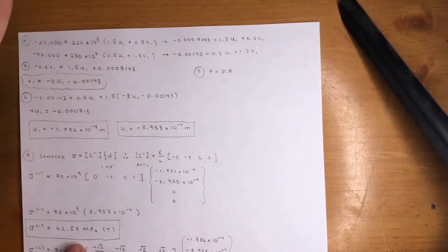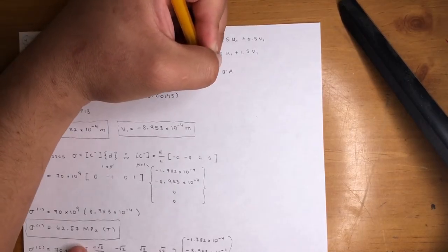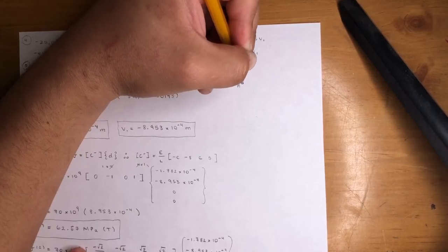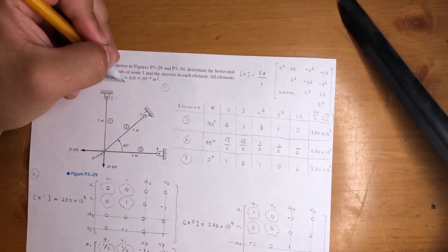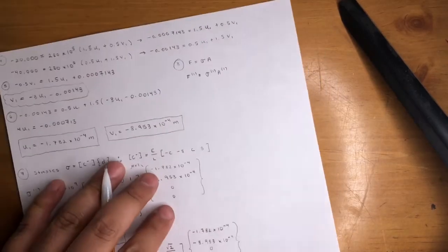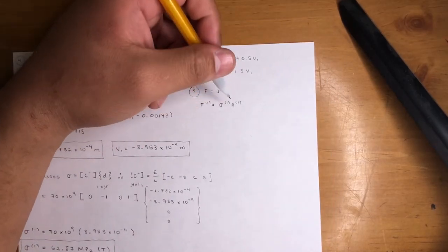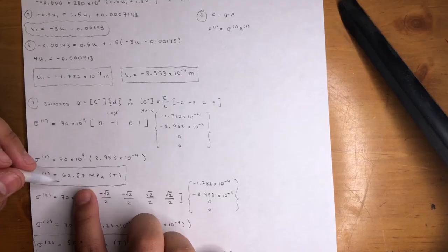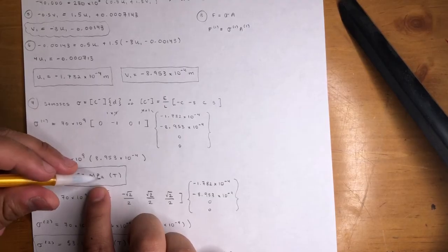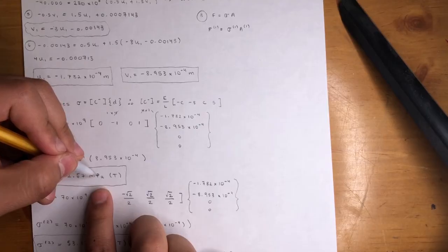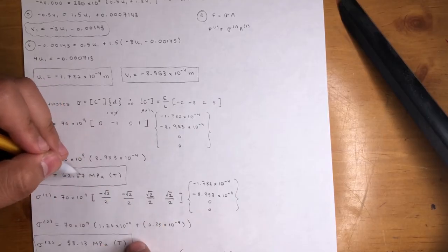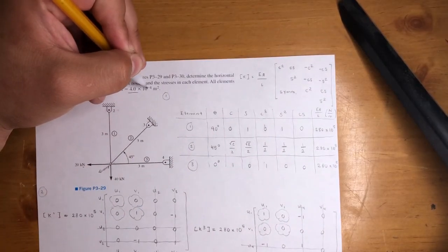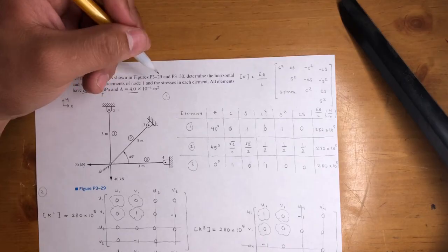So for the force 1, right here, sigma 1. Force 1 is equal to sigma 1 times area of 1. Now they all have the same area, but on the exam they might have different areas. You've got to be careful. That's why I like putting 1, just to make sure. But 62.67 times 10 to the 6 newtons. This is Newton per meter squared, right? A Pascal. So 62.67 times 10 to the 6 Newton per meter squared times 4 times 10 to the negative 4 meters squared. You're going to get newtons if you multiply them.